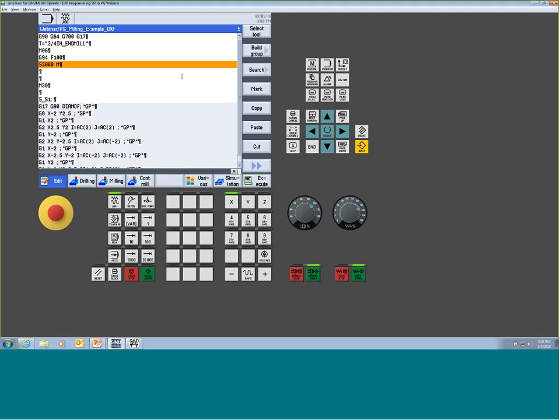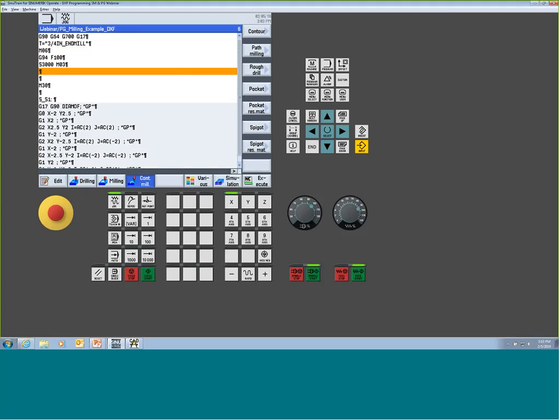All right. Okay. So let's say for argument's sake right now I'm ready to cut and I want to cut this profile, this shape that I just created. Well, at this point now, if I physically go in and use my contour mill, I can start to use these contour cycles with these shapes. So I'm going to first need to basically tell the system, just like I would have had I been doing normal G code, what the shape is and how it exists.